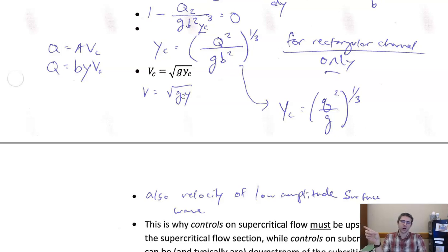But if I'm standing in water that's moving at the critical velocity this way, the waves that want to move upstream basically can't. So at this velocity, the V sub c this way cancels with the V wanting to go this way. And so the waves will just stand still, and none of those ripples can propagate upstream. Okay? They'll all go downstream, basically.